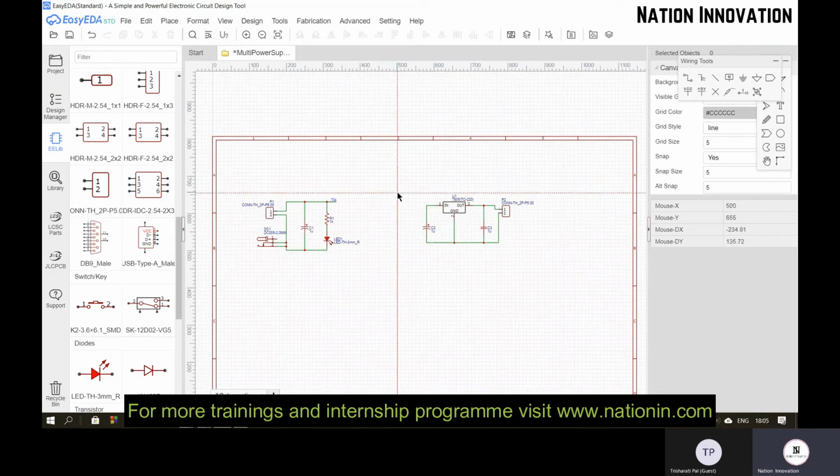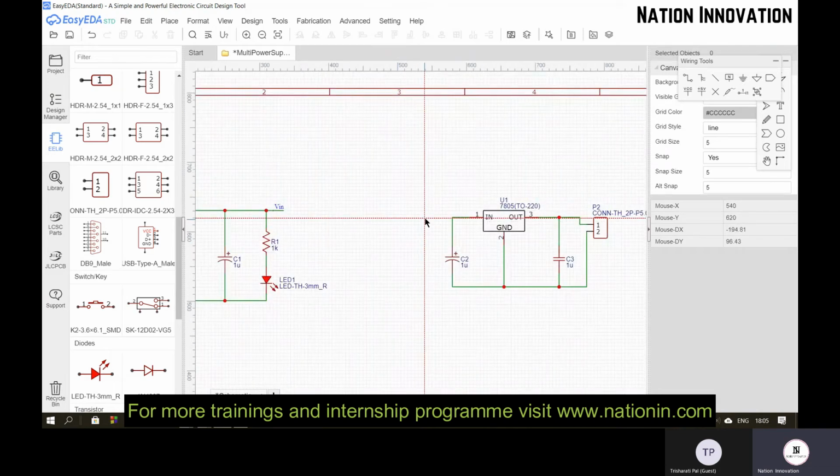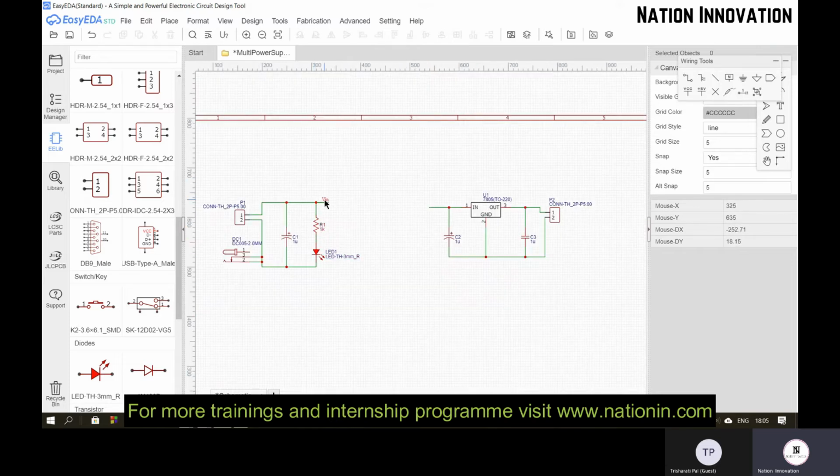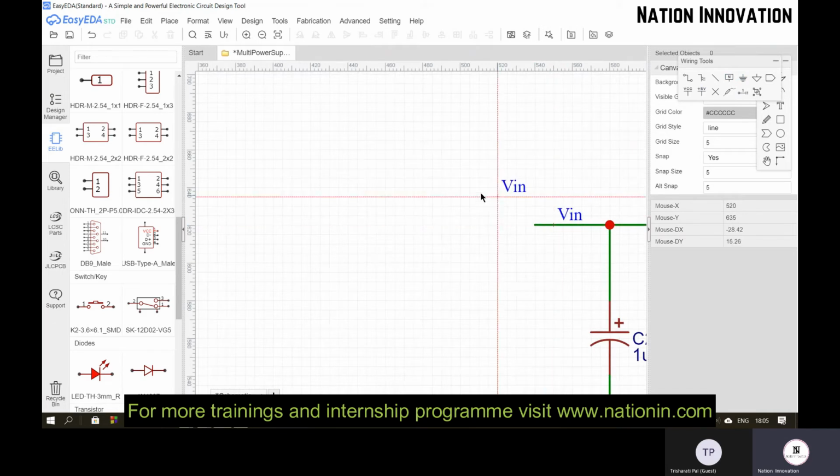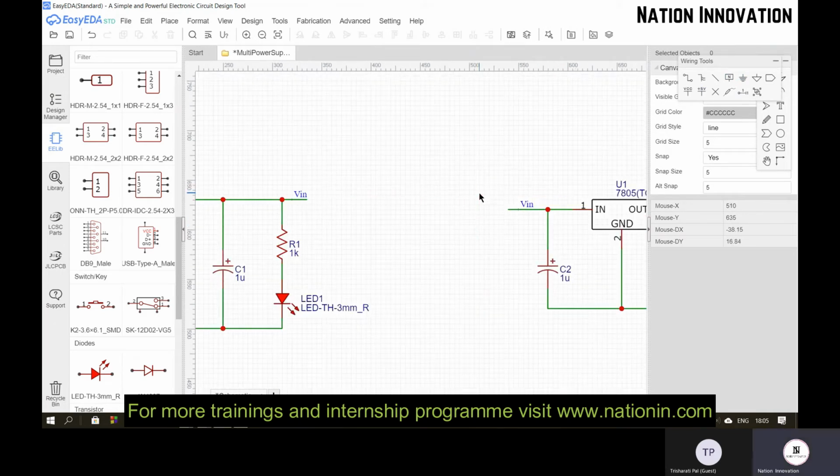Okay. So the input for this 5-volt voltage regulator will be the output of your DC power supply. This is your DC power supply. So whatever output is coming from this DC power supply, the same input goes to this 7805 IC. So for that again go to net label. This is the net label and place it on this line. So no need to connect an external wire from here to here.